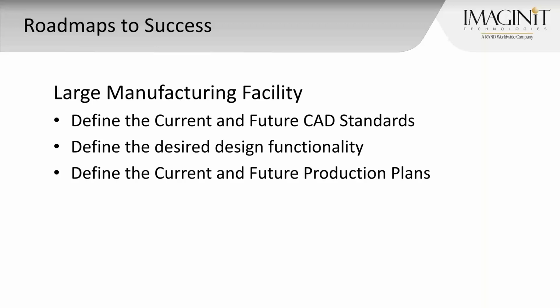The other thing is borders. Want to make sure that whatever borders were created historically, that as we move forward, we've updated those borders that are referenced in the AutoCAD version of borders. And so we can create that border and the title blocks for that, name it the same as the MicroStation borders. And then once it's translated, it's referenced into that drawing the same way it was referenced into the MicroStation drawing, but it's a new AutoCAD border. And so those borders can be referenced in. Again, not paper space, model space, but once those borders are in, you can run a script routine that will take that and put the model into model space and keep the border in the paper space. And so that's a common thing that we've done in these translation projects.